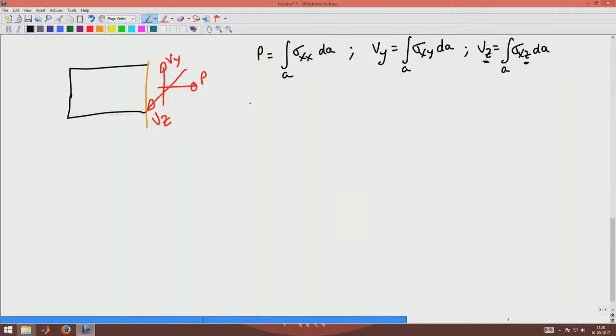Now, if the traction were to act uniformly across that section, then you will not have any moment when you take it about the center of the cross section, okay. On the other hand, the traction is not uniform in magnitude nor direction. So, what is going to happen is there are going to be 3 moments that are produced due to this traction, okay. So, let us compute the moment due to this traction. The net moment M is given by integral r cross f, where f is T^(Ex) dA.